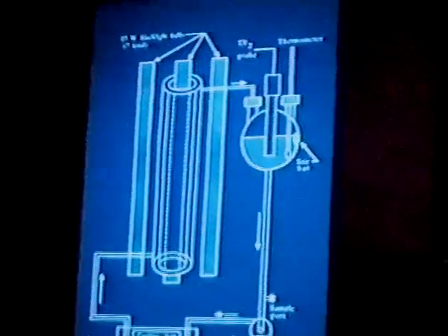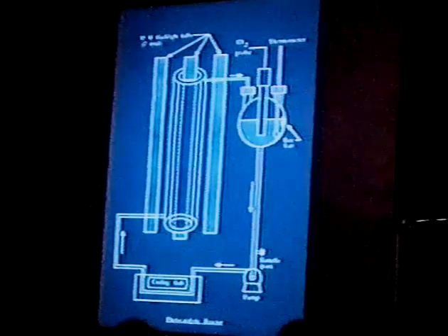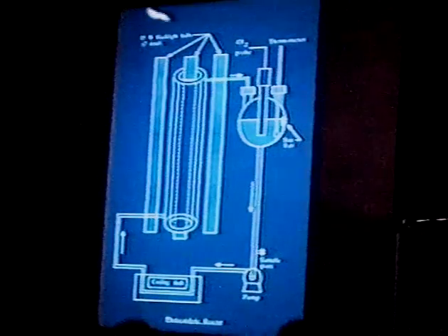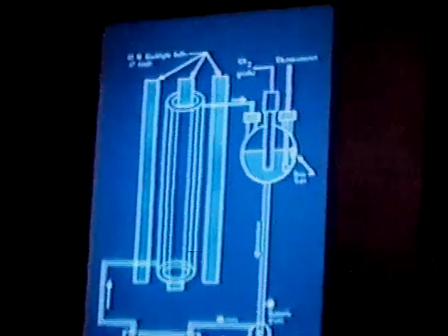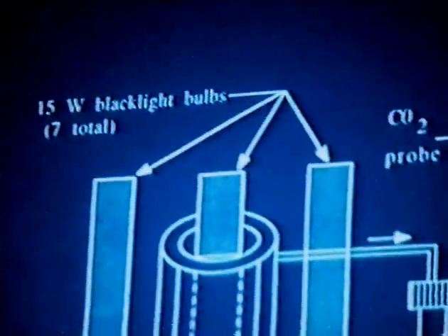The reactor we used for the photocatalytic studies is one we've used in our lab for a number of years. It's a recirculated batch system. The quartz annular reactor for the photocatalytic system is shown here. It contains one fluorescent UV light down the center line and has 6 other fluorescent bulbs surrounding the reactor. The solution is recirculated through a probe reservoir, which contains a CO2 gas sensing electrode and also a vapor headspace. The vapor headspace provides the oxygen that's necessary for the reaction.